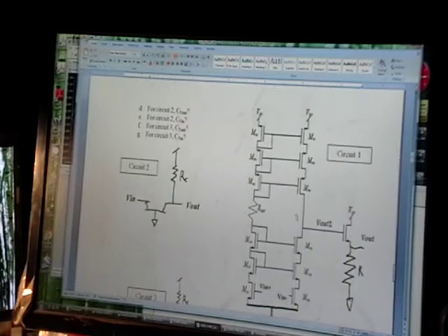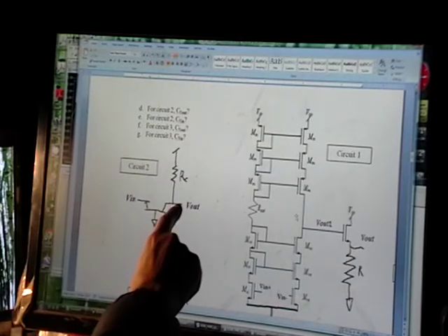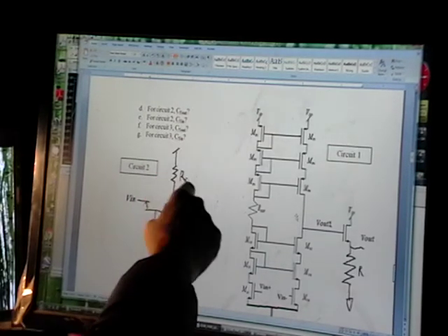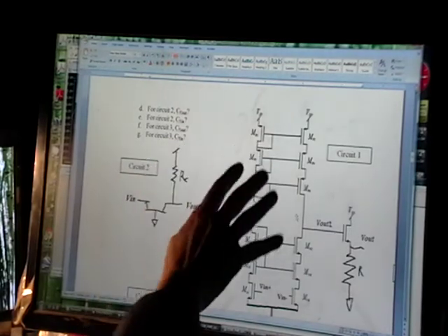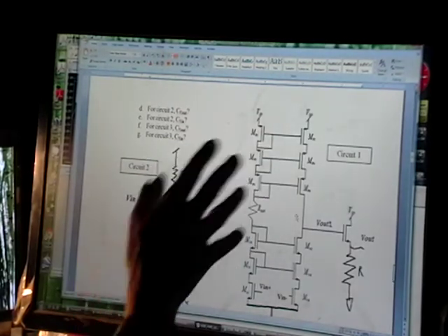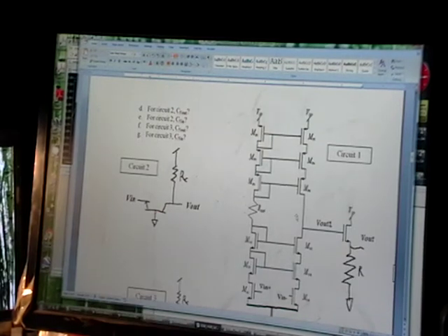Okay, 1D. Here's circuit 2 and asking for V out. So V out, if you're sitting here, you need to go in all directions to see what you hit, and up, it's just a resistor, so assume that there's no capacitance there ideally. And then here you're hitting the collector.